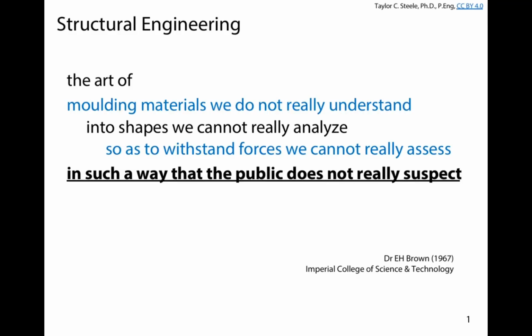So far in this class, we've been spending time talking about how buildings work, and specifically how steel structures work. We looked at how the framing in the floor system and the columns that support the floors are arranged to support gravity loads. For a uniform load, we trace through what the load might be on a joist, which is supported by the girder. So we trace the load through the joist and find out what the load might be on the girder. And then we trace the load through the joists and the girders that are framed into the column to figure out what the load on the column might be at each floor.